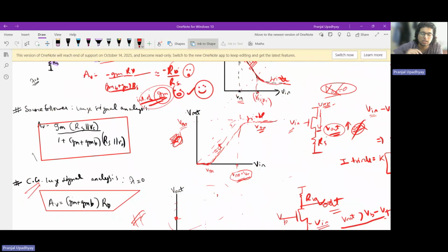So this is the kind of characteristic which we'll observe in large signal, and it won't just keep on going to infinity because eventually the device will transition to triode, with the condition that the gate voltage or the overdrive voltage is more than the drain voltage, right? Because the source terms will cancel out when you write the full equation. So that's the basic idea.